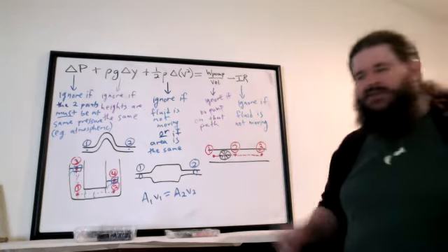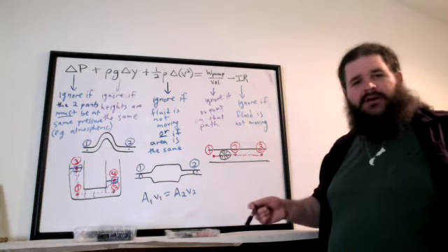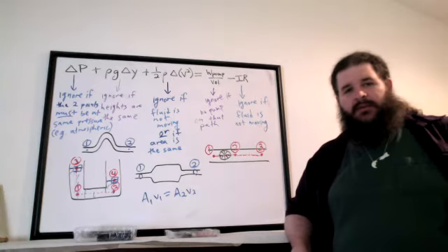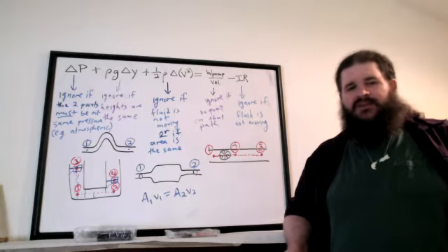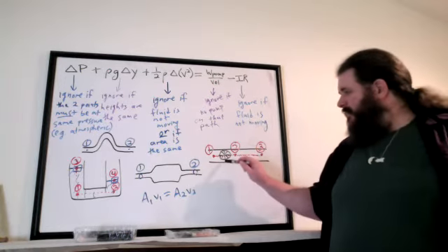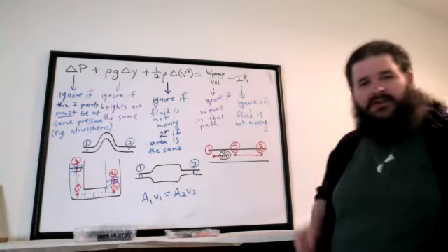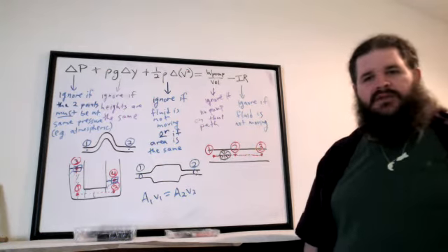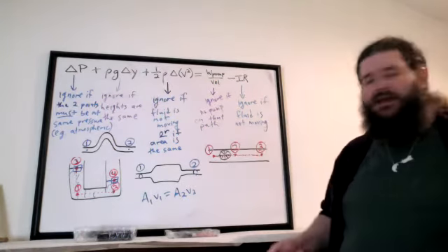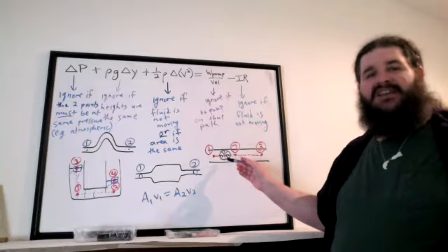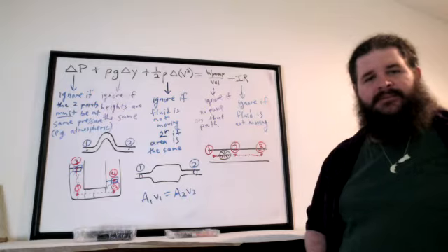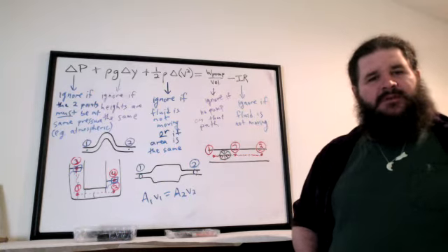So take a close look at the points you're comparing and draw out, on whatever diagram you have, a path from one point to the other. If that path goes through a pump, then you include the pump in your equation. If the path does not go through a pump, then you don't include a pump in your equation. Even if there's a pump in the system, you have to ask yourself whether the path you're considering actually passes through it. The whole point of a pump is that it creates a difference in pressure, or really a difference in total energy density: high energy density on one side, low energy density on the other, by pushing on the fluid. Any questions on that so far?